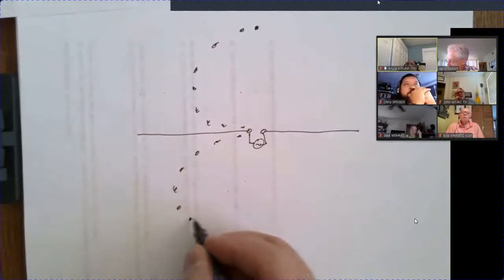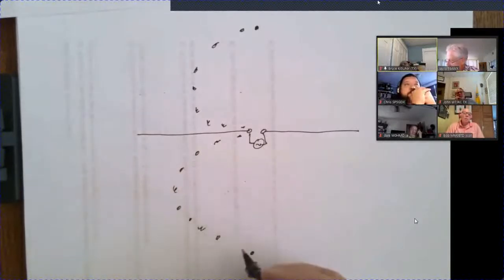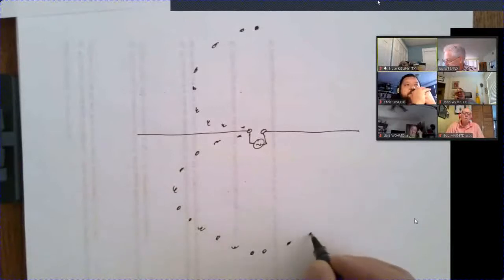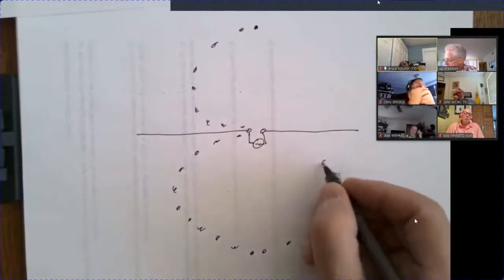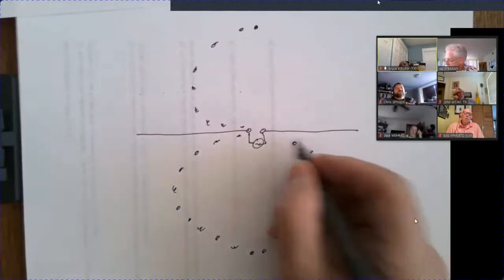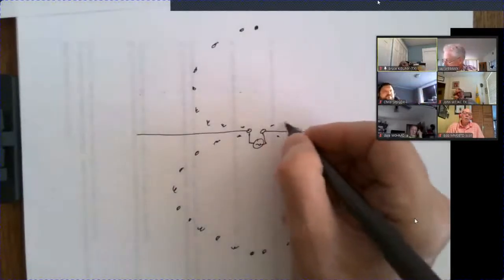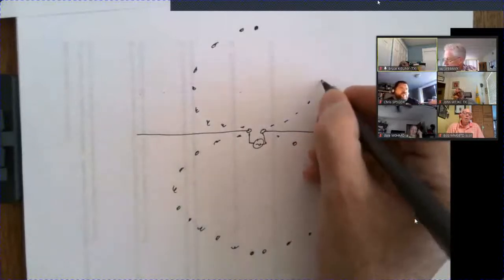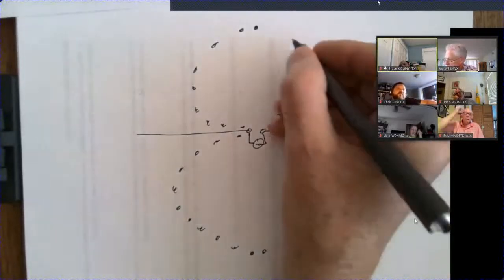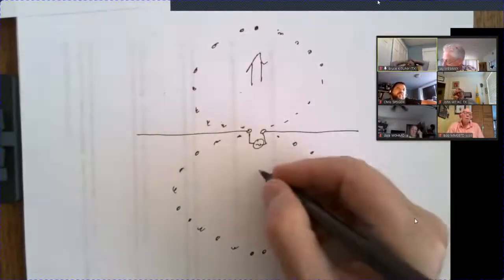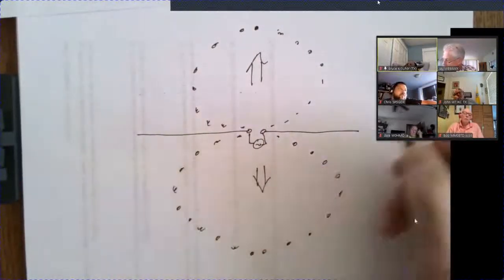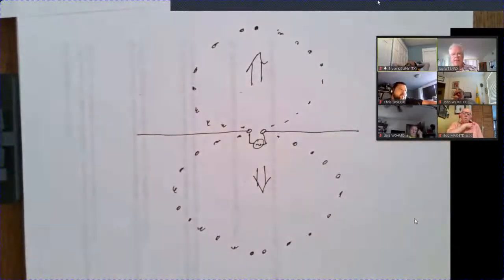I mean, you can take a meter or a radio and walk around your antenna if you really want to do that on a cold winter night. But you can figure out a pattern either mathematically or whatever. But this is the dipole pattern. It's like a figure 8. And you get most of the radiation in 2 directions. And there's practically none off the ends.